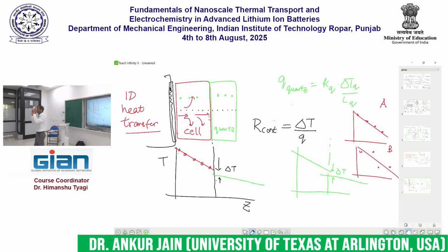If it was to go strictly in a straight line, then the temperature drop will be linear and you will get a tight fit here. But here it tells me that something is not right with either my measurement setup, my thermocouples, or something. I have to go back to the drawing board and figure it out. Does that make sense?